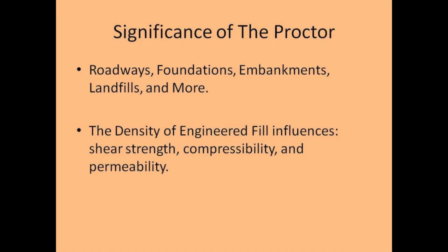A standard Proctor curve that is representative of engineered fill should always be used when compacting roadways, foundations, embankments, landfill liners, and many more geotechnical applications. The density of engineered fill influences shear strength, compressibility, and permeability of soils.